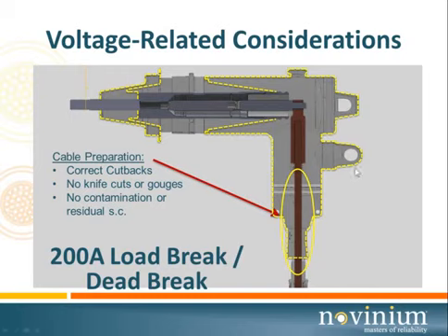It's important that we wipe from the inside, toward the cable. Always wipe in this direction. Why do we do that? If you wipe with a solvent from the cable shield down the insulation, we're going to drag carbon particles from the insulation shield down the surface of the insulation and contaminate things even worse. So now let's assume we've got no contamination, everything's clean, ready to go.